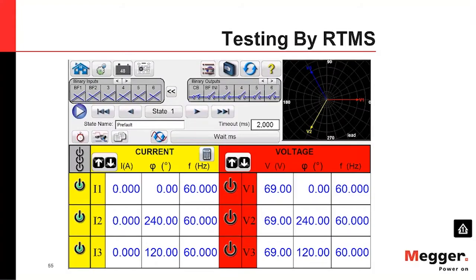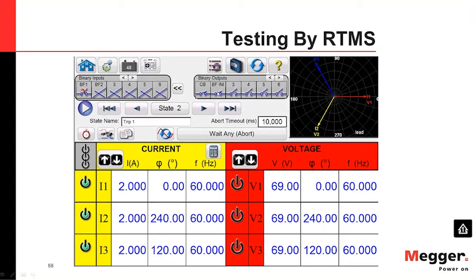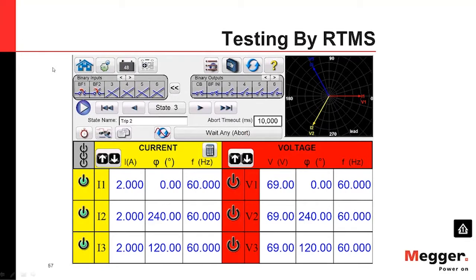So what I have done here, we have done a circuit breaker close, and then this is stage 1, and as stage 2, I put BF INI with the current over there, and then I'm waiting for my trip as BF number 1 to have the timer. And if that did not clear because the breaker is defective, there is no DC or whatever, it will go for BF number 2, and it will wait for the contact to trip, and then I'll have my timer number 2.